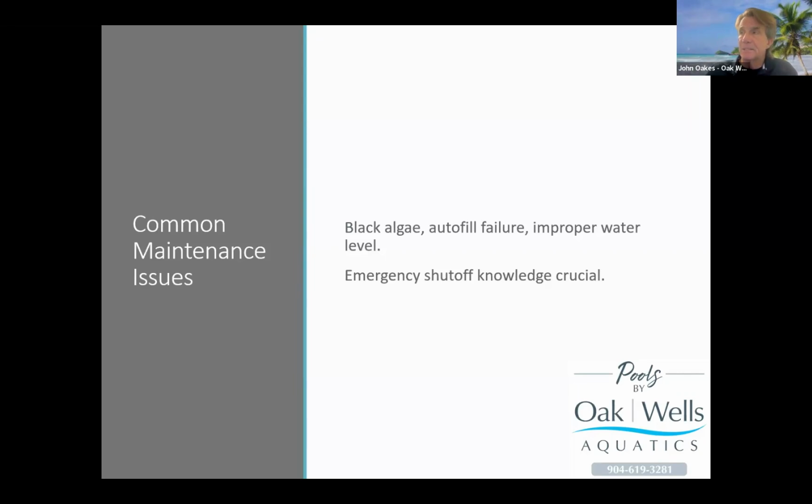It's leaking someplace. And if the reverse of that turns out to be true, that the bucket loses more water than the swimming pool does, somebody either monkeyed with your test or your autofill is still on. So you would need to turn the autofill and the pumps off during a leak test like that.